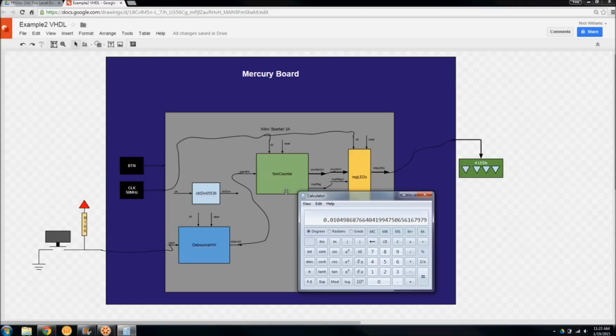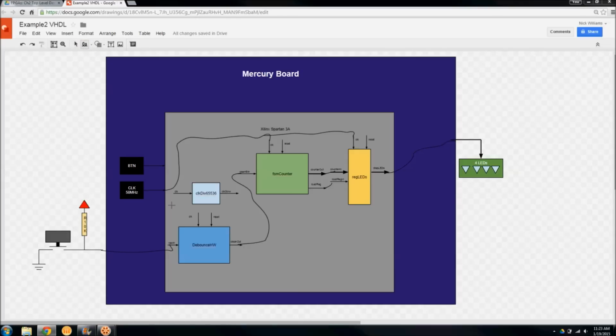So just with this simple math, we can see that this clock division will slow down this debounce hardware enough that we can successfully verify any button presses made here. So I'm just going to connect that now. And then obviously these resets will get attached to this button here.